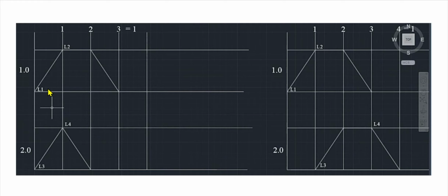And then this L1 will trigger Y1 and Y3, and then L4 will put back cylinder 2.0 because it will trigger Y4. So this is Y3 and this is Y4. And then L3 here will be pressed, and this will enable cylinder 1.0 to retract.